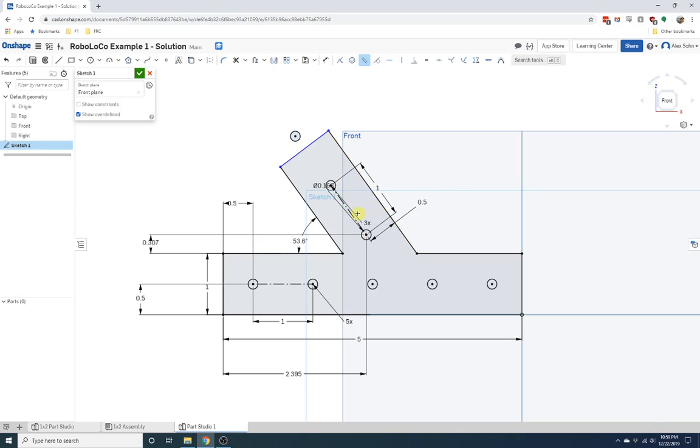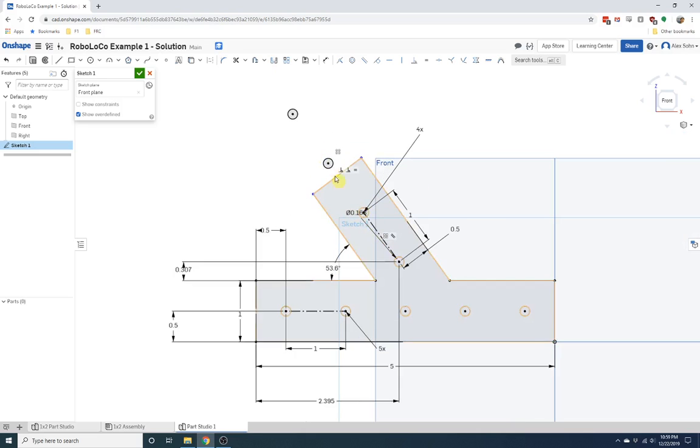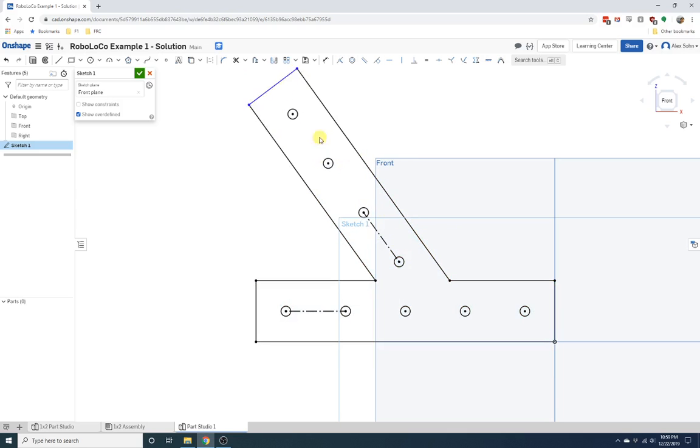There you go. So let's just say later on I wanted to add another few holes. So we're going to make this 4 holes. I'm going to say 4. See, it continues in that direction, right? So you notice how my holes are going longer than the bracket, right? See how this is blue. It's not constrained. So I want to constrain it to the last hole.